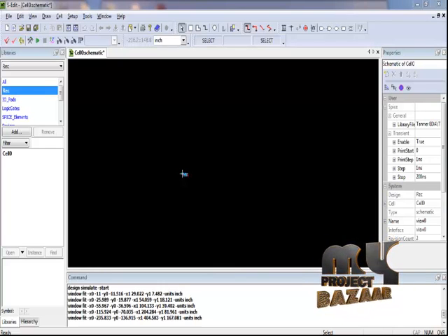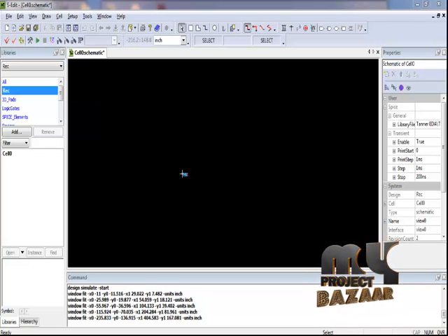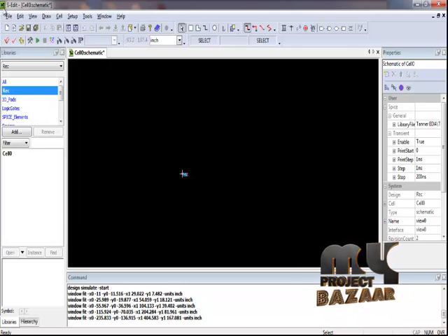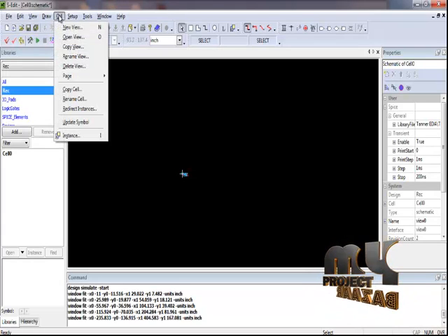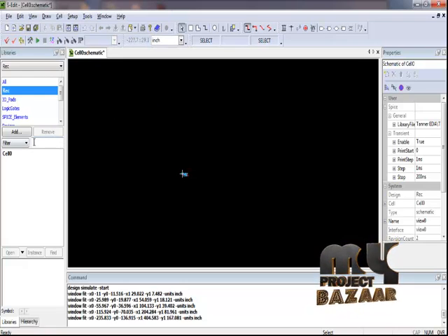Next we are going to see the output for our product. We create the design in Tanner version 13.0. To create a new project, we have to click on file, then new, and then new design. For the cell creation, you have to click on the cell and then click on new view. We can change the cell name.